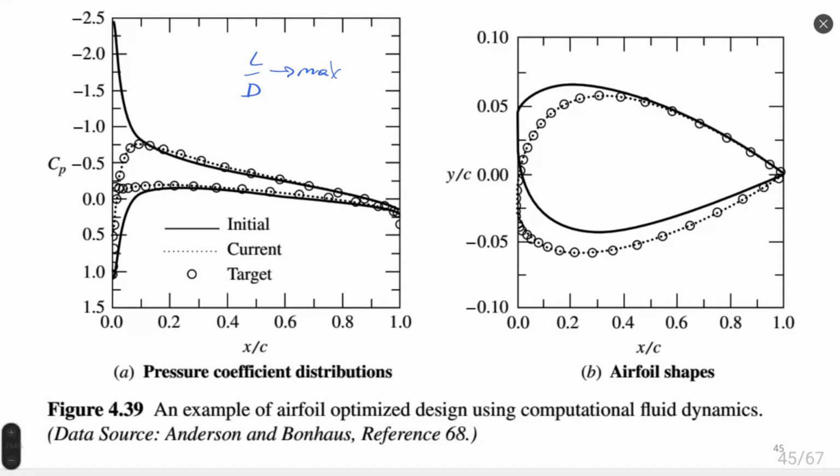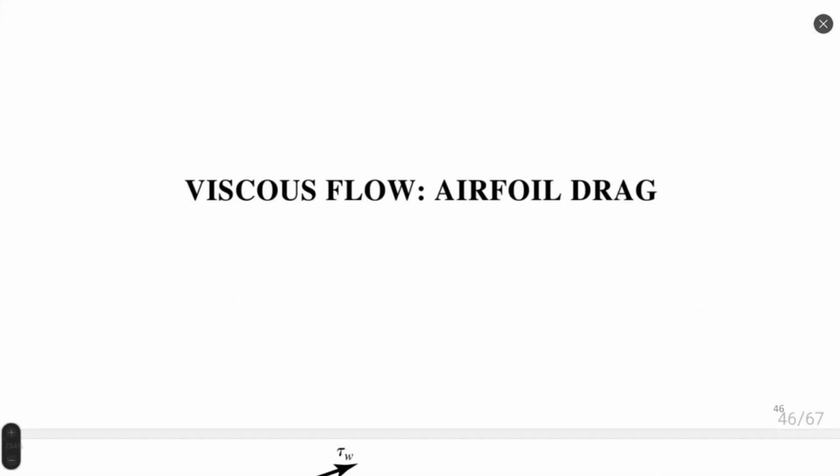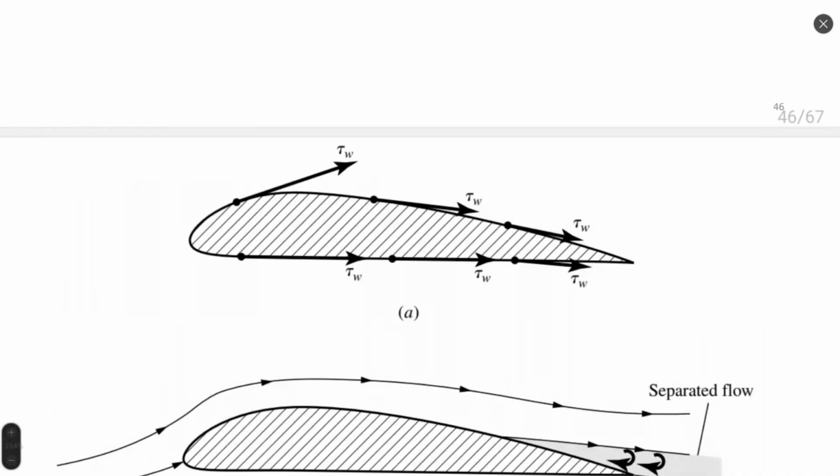And these changes result in significant improvement of airfoil performance, as you already saw from the previous picture, can be 15–20%, more or less in this range, improvement of lift coefficient. And in many cases, improvement also of drag coefficient.